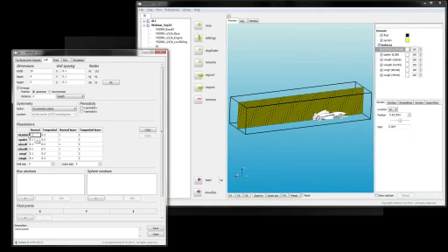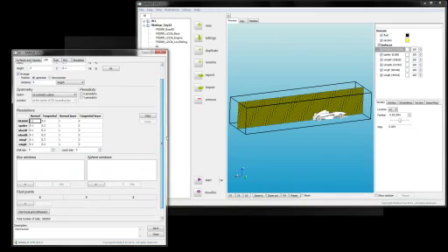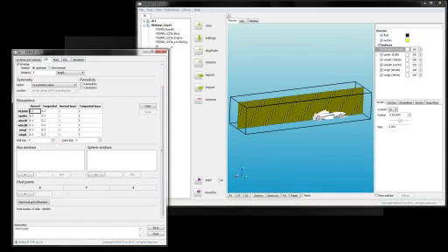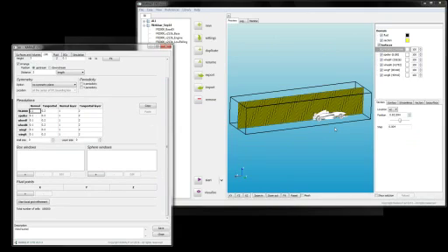Then here in this part of the panel, it allows me to put some grid refinement parameters on the surfaces of the car. And then the LGR, when it starts generating the unstructured grid, would take note of those parameters. So these are the normal dimensions, and these are the tangential dimensions of the grid. And with these, one can control growth rates. I'm going to leave that aside at the moment. So 0.24, 2 centimeters, and 4 centimeters on the car.